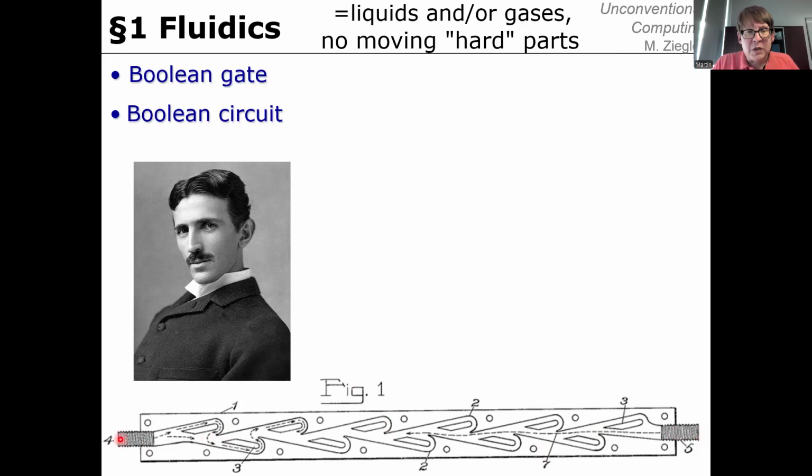So it is possible for fluid to go from here to here, but only very slowly, and only when there's no pressure. Then it can gradually drip through all this. But with high pressure, it produces a high counter pressure, preventing flow, so only in one direction, but not in the other. So in this example, there are 1, 2, 3, 4, 5, 6, 12 of these turbulence creating devices. Can have more or less, but this is a very interesting basic principle.